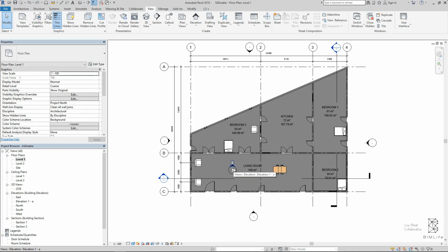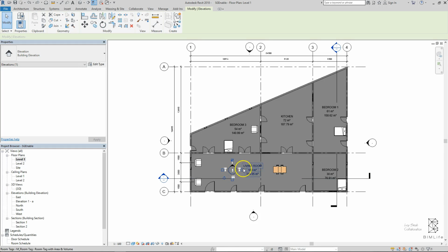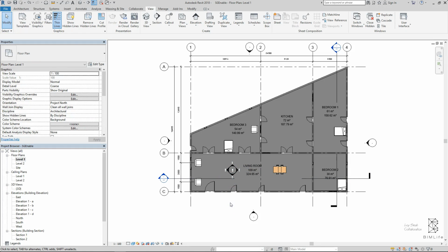To create elevations of different directions in your room, simply click on the body of the elevation. You will notice some of the elevations are unchecked. Simply check all sides of the elevation. Now you have 4 interior elevations of a particular room. You can access the elevations that you have recently created again by doing a double left click.